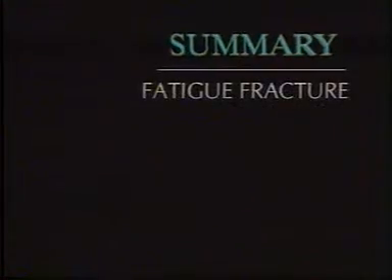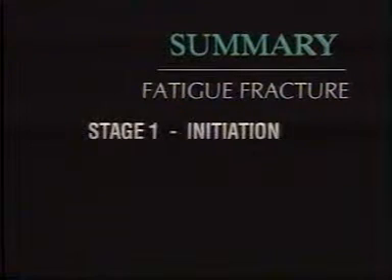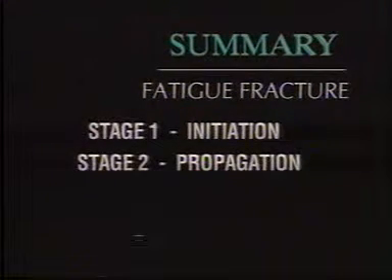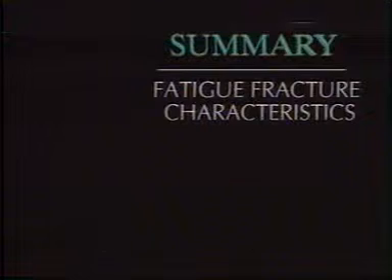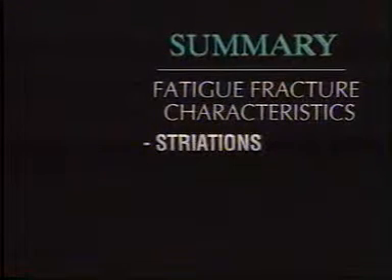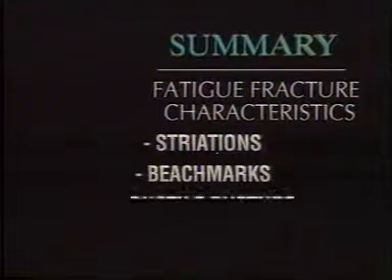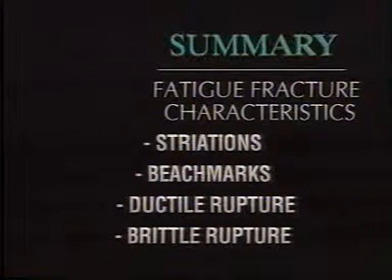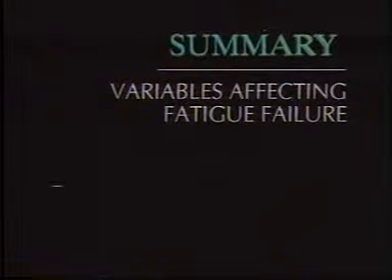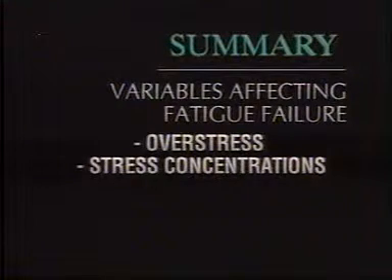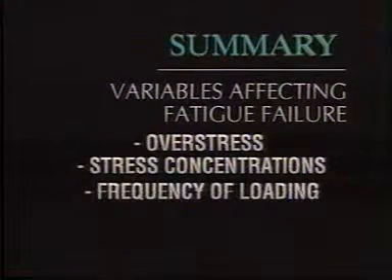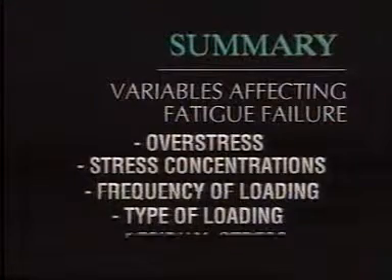Summary: fatigue fracture. Stage 1, initiation. Stage 2, propagation. Stage 3, fracture. Fatigue fracture characteristics: striations, beach marks, final rupture, ductile or brittle. Variables affecting fatigue failure: overstress, stress concentrations, frequency of loading, type of loading, residual stress.